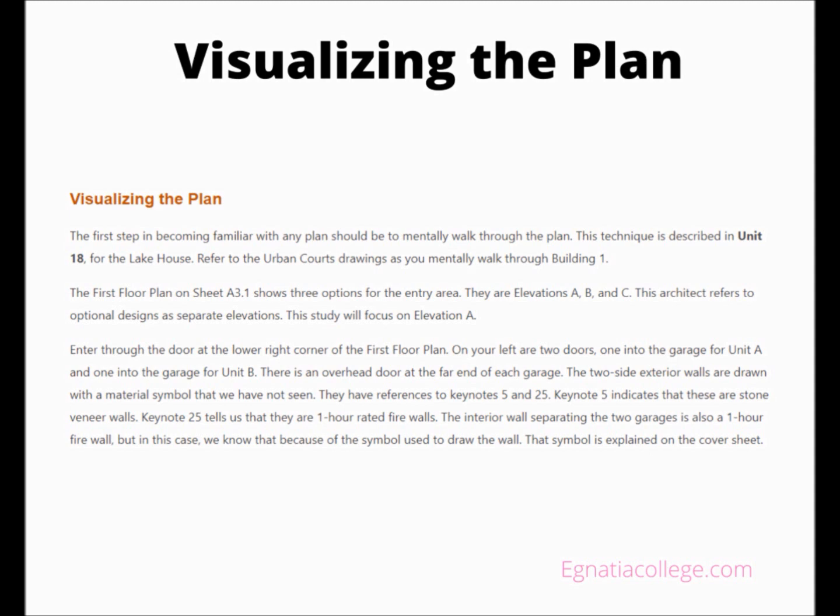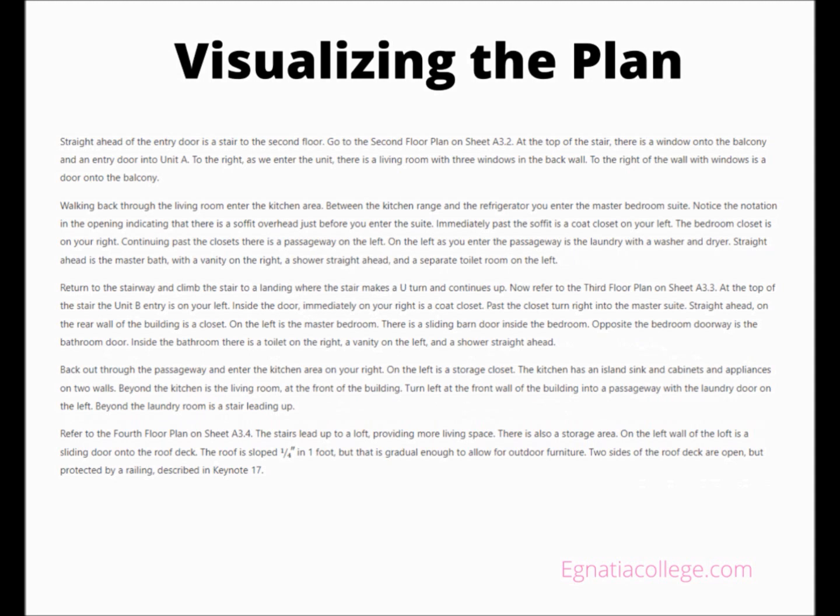The interior wall separating the 2 garages is also a 1-hour fire wall. But in this case, we know that because of the symbol used to draw the wall. That symbol is explained on the cover sheet. Straight ahead of the entry door is a stair to the second floor. Go to the second floor plan on sheet A3.2.